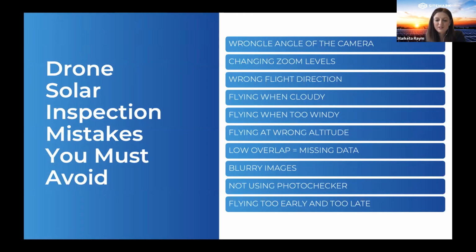Another point, if we have missing data, meaning the low overlap, that will impact the whole data analysis, as will blurry images. And then also really the timing. I can see this happening very often: not to fly too early, not too late, pick the right time, the right weather, and then you are halfway to a successful mission.